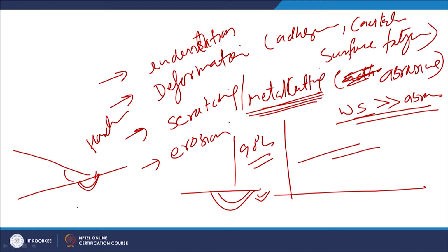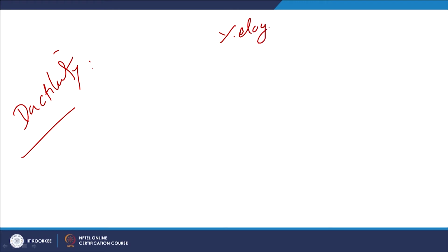So, these are some of the ways by which hardness affects the removal of the material from the functional surfaces. Ductility is another property. We know that ductility is about the extent up to which a metal can be elongated prior to the fracture. It is measured in a number of ways, such as percentage elongation until the fracture in the tensile stress strain diagram. Like say this is the strain.